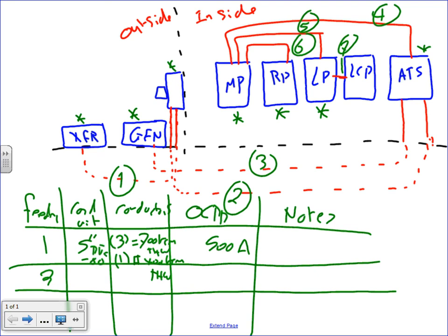Any question, guys? Any question? Ashley, anything underground is PVC Schedule 80. Anything above ground is EMT, inside. If it's outside, like these conduits, these little 2 conduits here, I would use rigid metal conduit if it's outside.